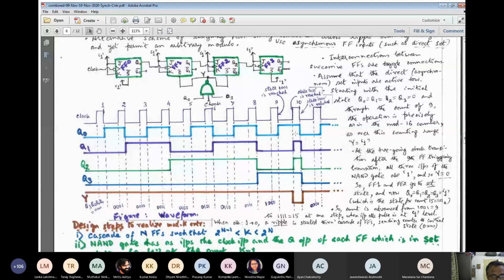Now that you have raised a very nice, very pertinent question, it actually facilitates the discussion. The on-time duration of the clock should be, for safety, kept larger than the sum total of two NAND gate delays.